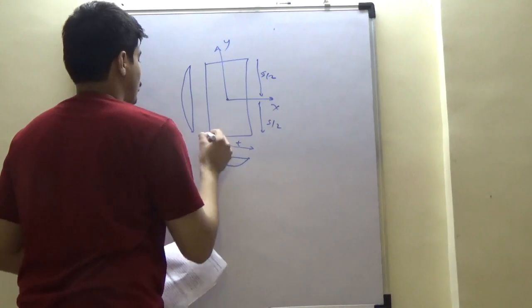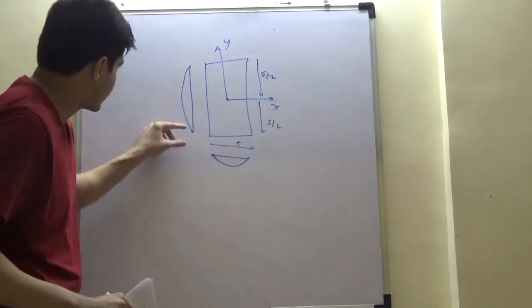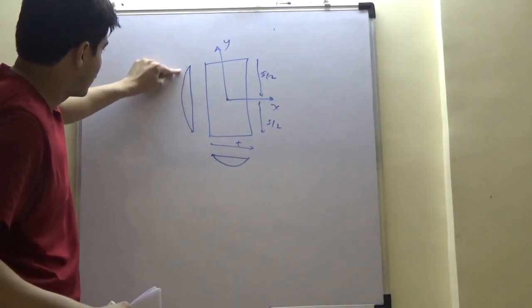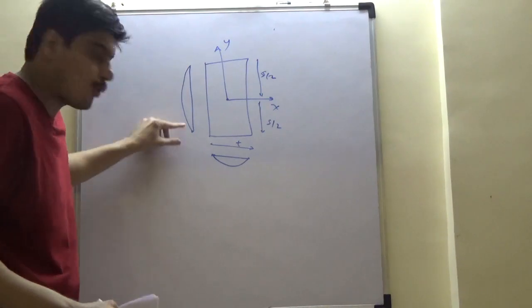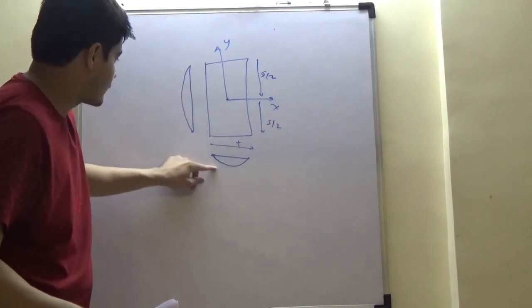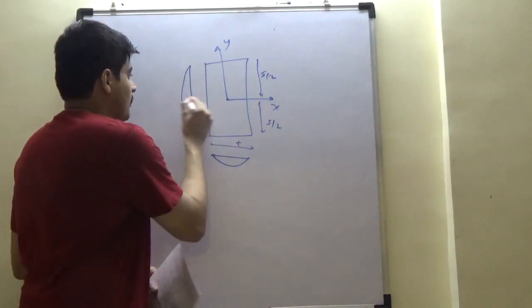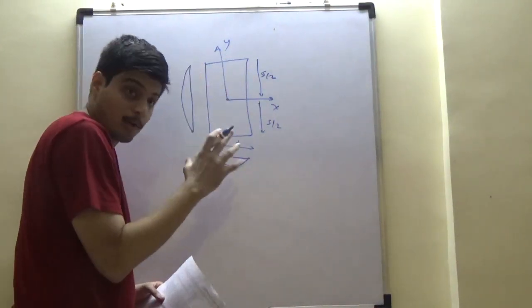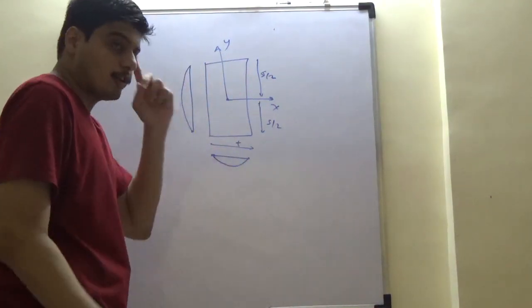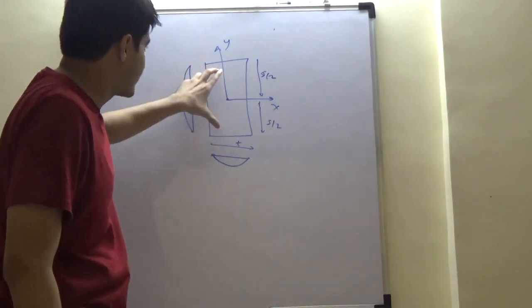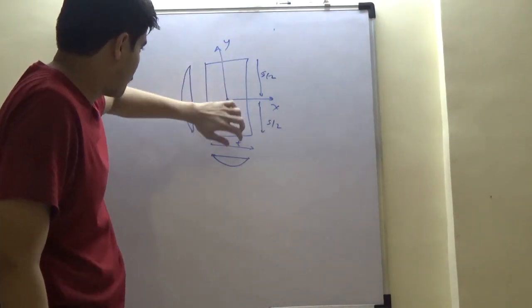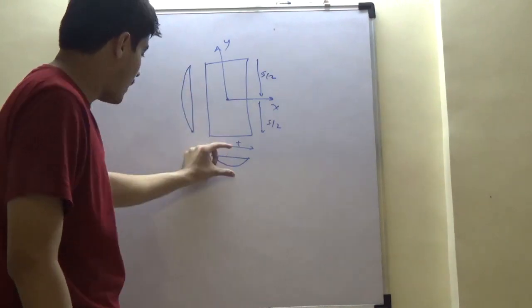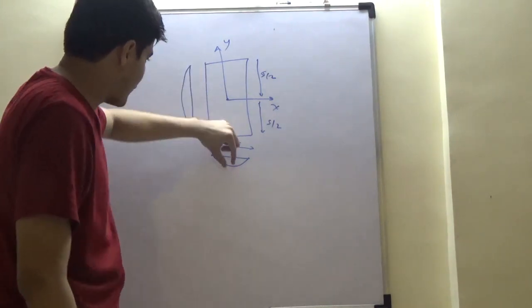What we have said is, if you see carefully, since boundary conditions will tell you that they have to satisfy no force, no shear and no strain conditions, the functions which we look for stress or strain will be something like this parabola, right? Maximum here, like a membrane. Now look at this as a membrane. Membrane analogy gives you a good handle on physics. So it is like this membrane, which is going to expand and collapse, and expansion is maximum here, like a warping function.